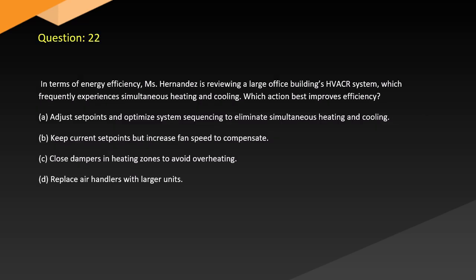Question 22. In terms of energy efficiency, Hernandez is reviewing a large office building's HVACR system, which frequently experiences simultaneous heating and cooling. Which action best improves efficiency? A. Adjust set points and optimize system sequencing to eliminate simultaneous heating and cooling. B. Keep current set points but increase fan speed to compensate. C. Close dampers in heating zones to avoid overheating. D. Replace air handlers with larger units.